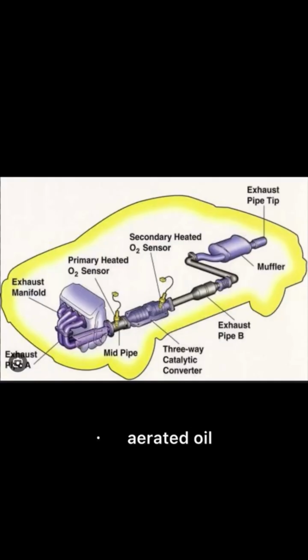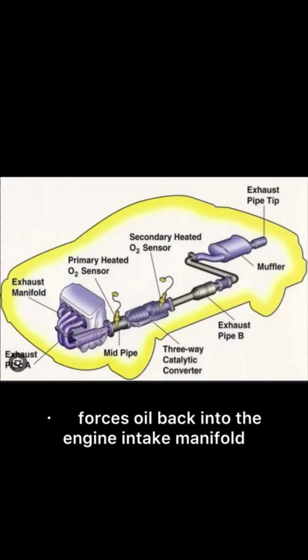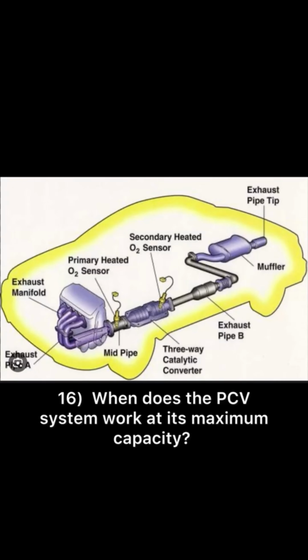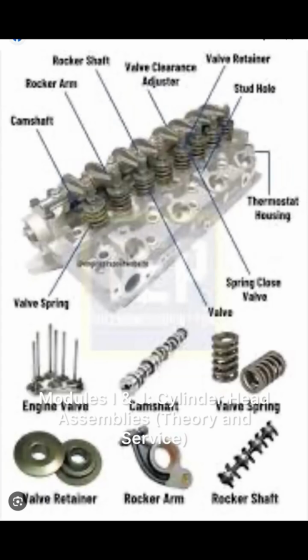15. What can result if a PCV system has a restriction? High crankcase pressures result. Forces oil past the engine seals, forces oil back into the engine intake manifold. 16. When does the PCV system work at its maximum capacity? Full engine load conditions.